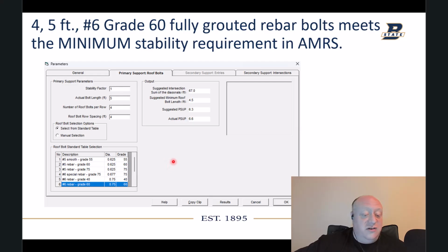But generally speaking, when I was in industry, the number 6 rebar, 3/4 inch, was the most widely used. I don't know that that's still the case. A lot of the mines, back in that time, we were considering trying to drill like an inch and a 32nd hole or an inch and an 1/8 hole or something like that to install a 7/8 inch bolt, a number 7 rebar, right? That's what we were originally going to try to do.